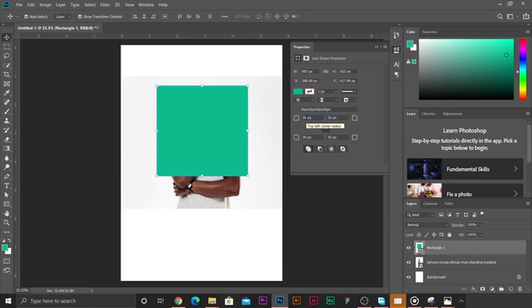Then let's choose to make one side 50 pixels. But you know that if you click the enter key right now, every other angle will adjust. Since we don't want that, let's click on this link here. Once I click on this link icon in between, you see that it is no longer highlighted. Once I click enter, I have 50 here and 30, 30, 30. Let me also try 100. I click enter, and you see I have 100 and the other angles are 30 pixels.